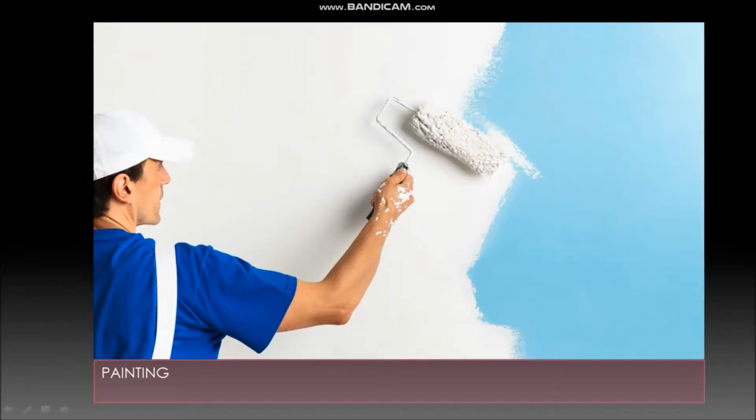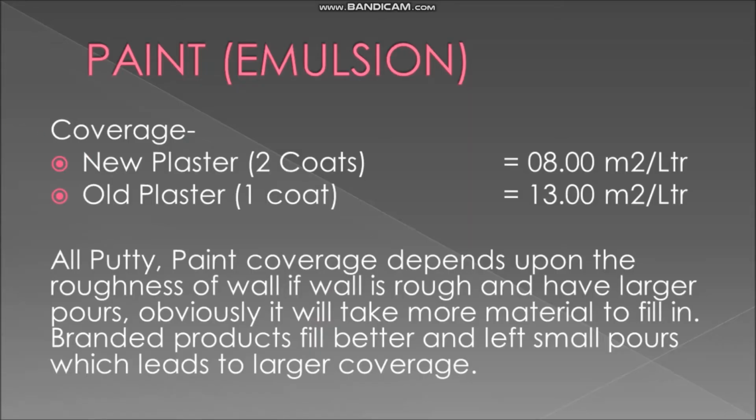Paint emulsion. We are now talking about the emulsion paint. There are various types of paints whose coverage varies from product to product. Now we are only talking about emulsion paint. Coverage of emulsion paint in new plaster for 2 coats is 8 square meters per liter, and for old plaster 1 coat is 13 square meters per liter.